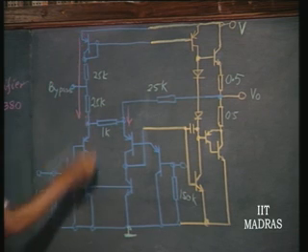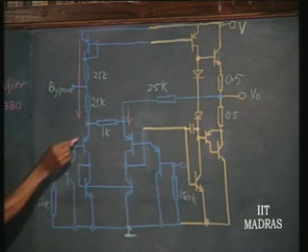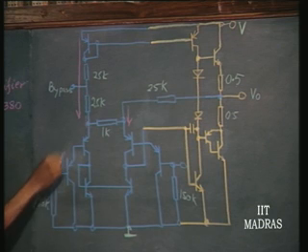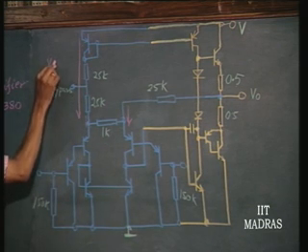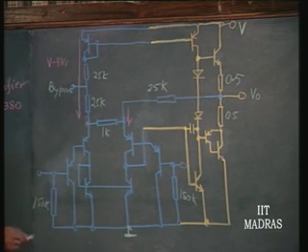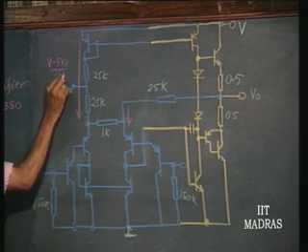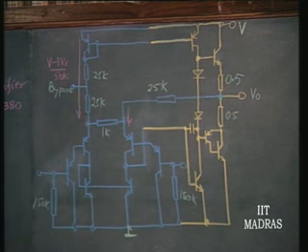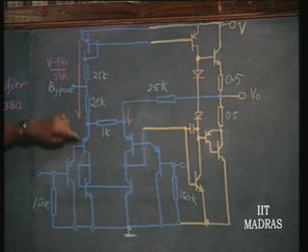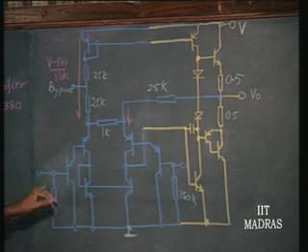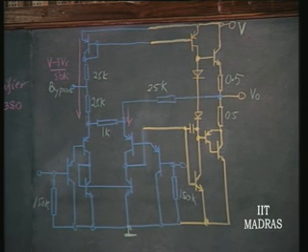V. One diode, okay, two diodes, sorry, one diode, two diodes, three diodes. So, V minus 3V gamma divided by 50K. That is the current in that. V minus 3V gamma, neglecting the drop in this, assuming that the beta of the transistors are high. Okay. V minus 3V gamma divided by 50K is the current.